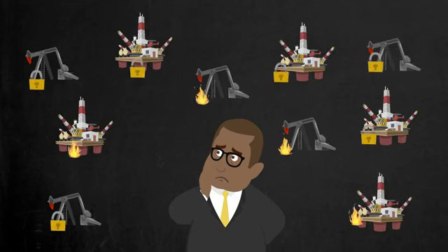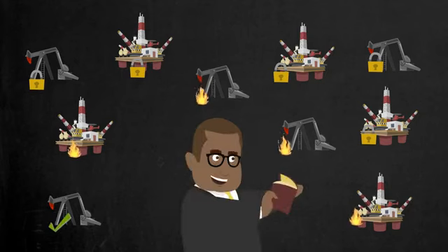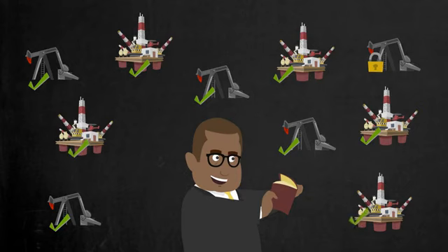For example, if the safety shutdown is overdesigned, it can be overly sensitive to nuisance trips, which will lead to unnecessary shutdown startup conditions. Overdesign can also lead to excessive capital and operational expenditures, which would impact the return on investment on a project. Using the LOPA methodology can help companies meet the ALARP principle, since it allows the company to define a specific target for what is considered reasonably practicable. Let's take a look at how a company's standard for using LOPA can help an organization make more consistent decisions.